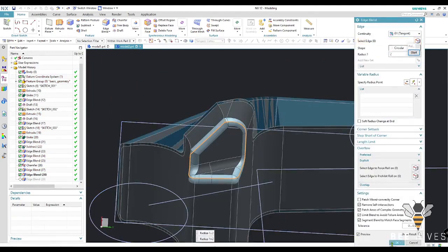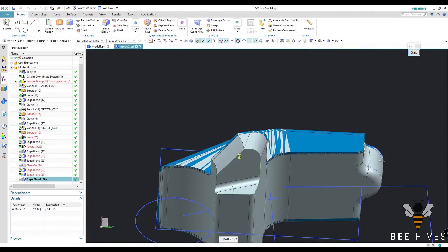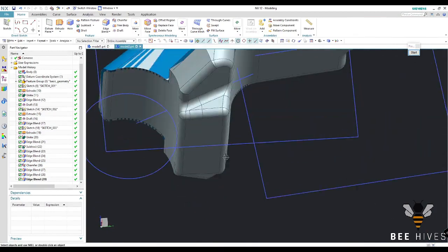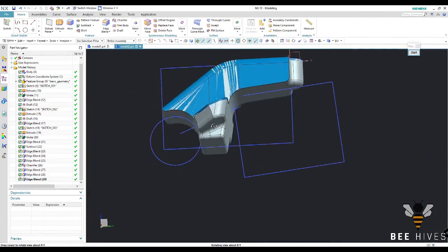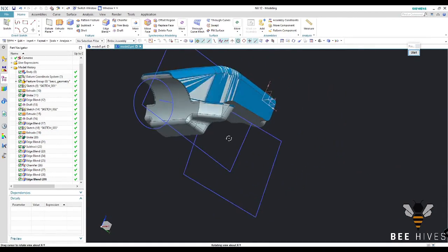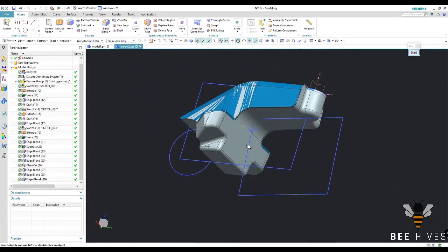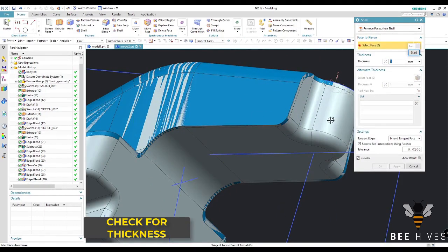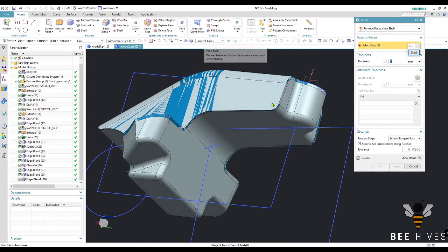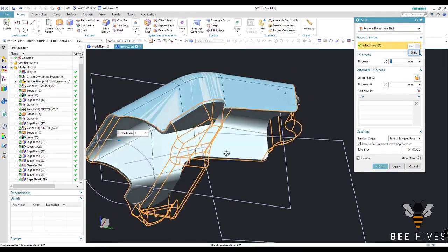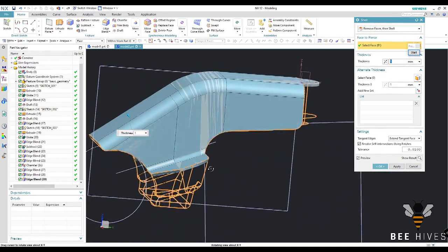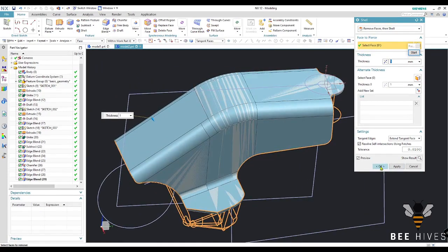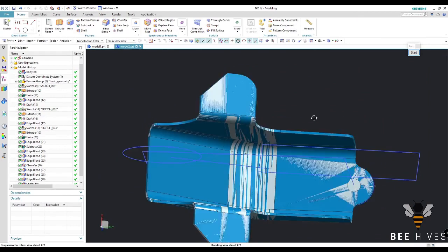I'm going with this. I'll simply click on this also because we need to take off this face as well. So this is how your solid model is created, and then finally apply the shell command. Shell, use the thickness, what exactly it is. Give a single face, use tangent faces, and this is how each and every face will get removed. When you applied the blends, it was all in tangency, so it gets removed. Say OK. Now this is how you can match the component.